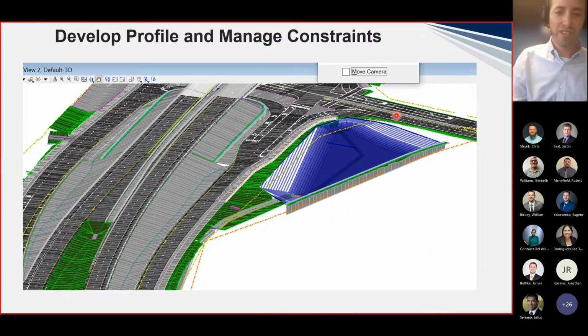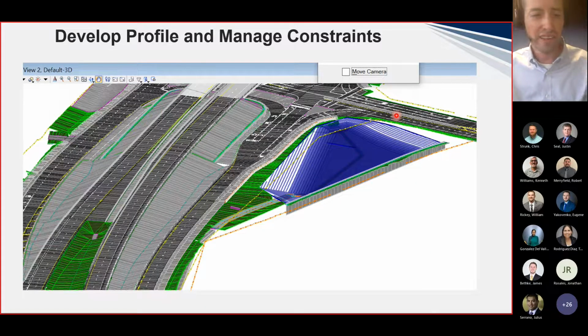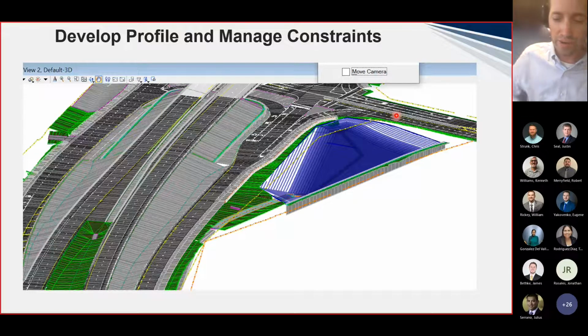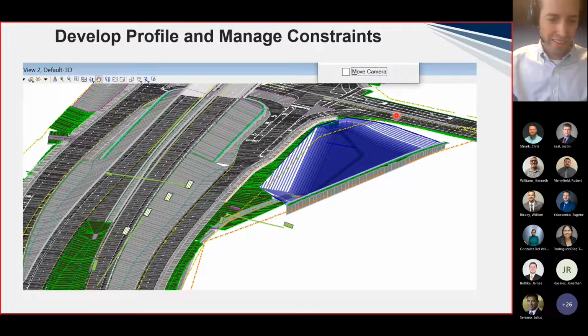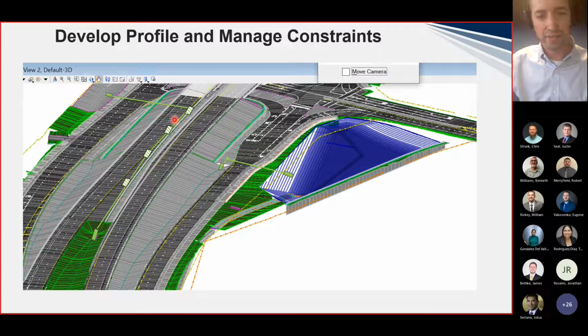So this is showing off a little bit of William Rickey's open roads corridor work that for this area we were looking at. So this is the southbound side where we captured the water in SET, and this is the series of inlets that we show, and dropping it, going under the frontage road and outfalling into a ditch.